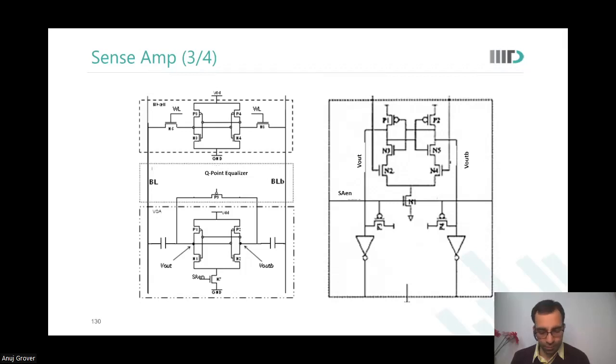Sir, I feel more than benefit, there is a loss actually, because there is a delay in writing the BLB, or bitline bar, towards the internal node. So why is there a delay? Okay, so ma'am, capacitor, what is the benefit? Why would one consider putting a capacitor instead of the pass gate?